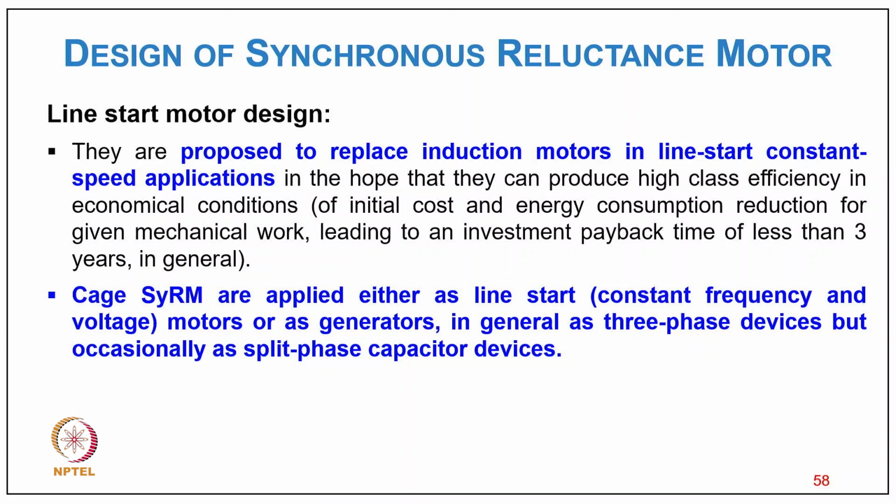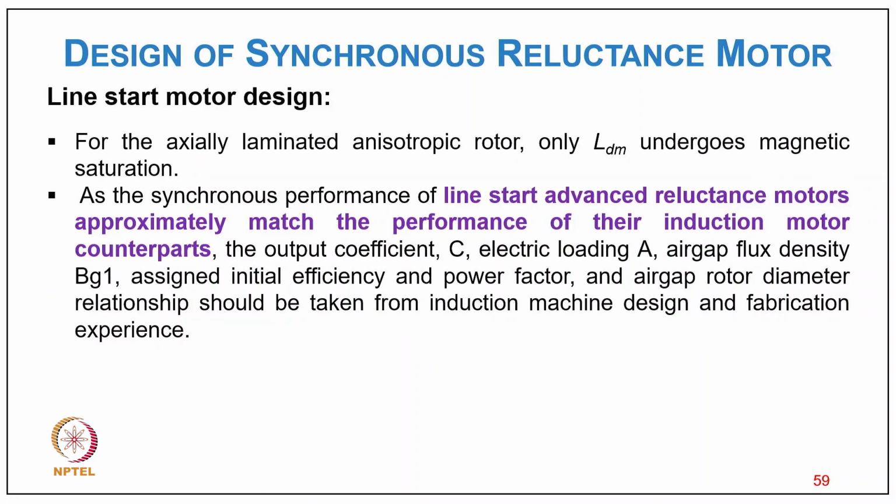And cage synchronous reluctance motors are applied either as line start constant frequency and voltage motors or as generators in general three-phase devices, but occasionally as a split phase capacitor device. For the axially laminated anisotropic rotor, only Ldm undergoes magnetic saturation. As the synchronous performance of line start advanced reluctance motors approximately matches the performance of their induction motor counterpart, the output coefficient, electrical loading, air gap flux density, aside from initial efficiency and power factor, and the air gap rotor diameter relations should be taken from induction machine design and